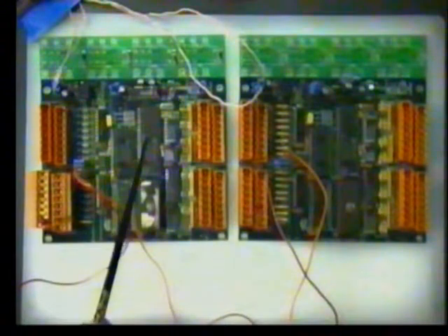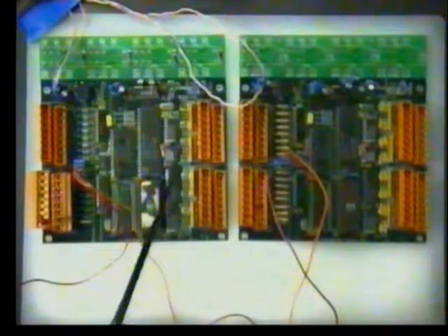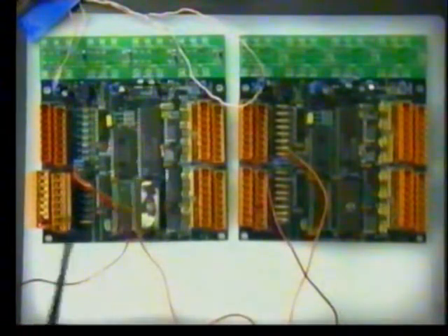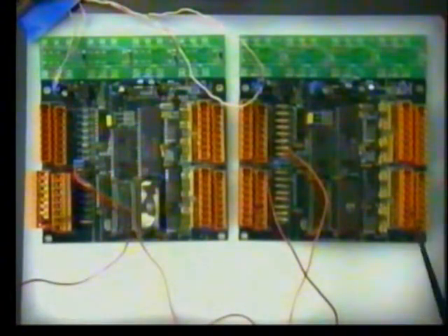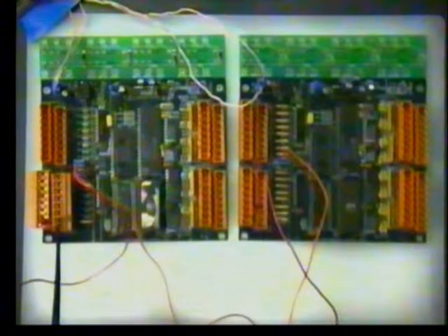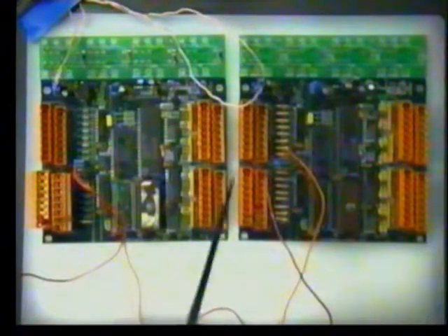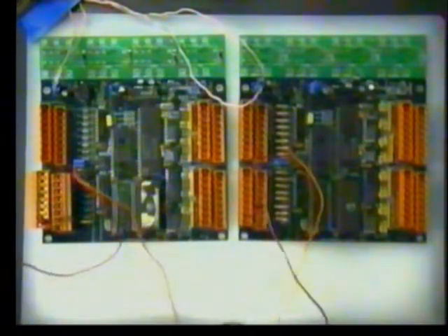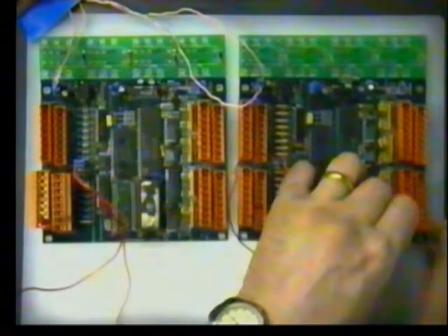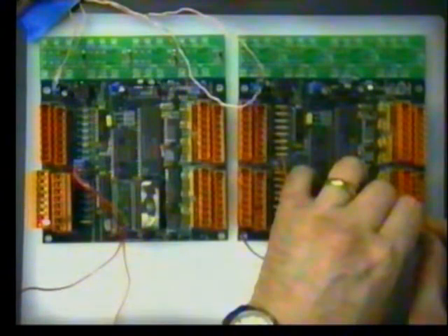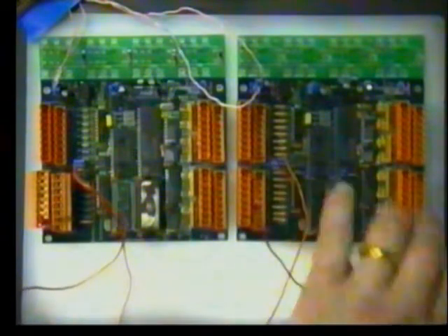And this unit has been tuned to receive that channel off of this board. And what I've done is I've mapped that data to these outputs. So what I'm showing here is a switch closure on this board is being used to enable an actuator. This is a high voltage output on the second board, which is connected only by the wires. So here we come in onto board 1, close the switch, and then we see it's actuated by the LED coming on.